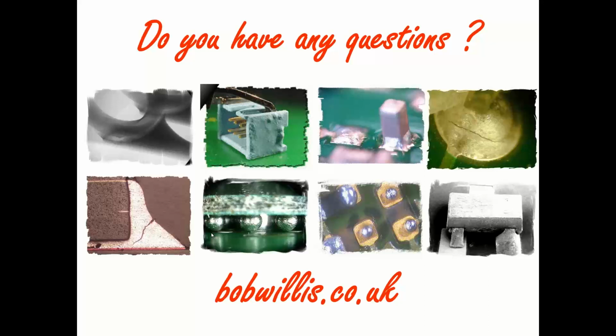Okay, so a question just came in about rework of BGAs. Well, I don't find it difficult to rework a BGA that's been conformally coated, unless the conformal coating has literally been flooded underneath the part, which ideally you shouldn't do because of the potential for expansion and contraction failures. Because the coating will just be around the outside of the BGA, it will not be underneath. There might be a little bit underneath under the first row of balls or second row of balls, but that's about it. So fundamentally, the removal process is pretty much straightforward, the same techniques.